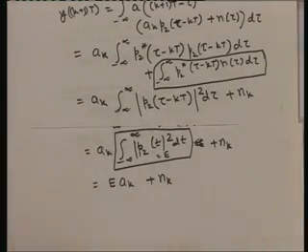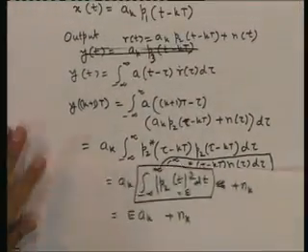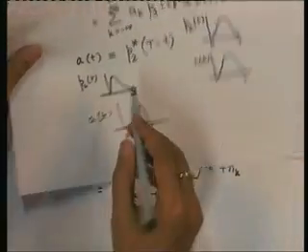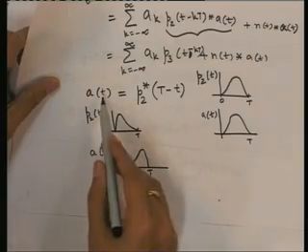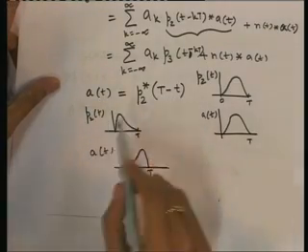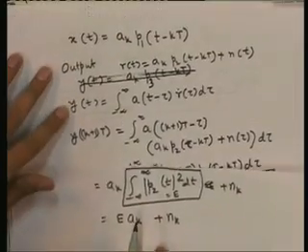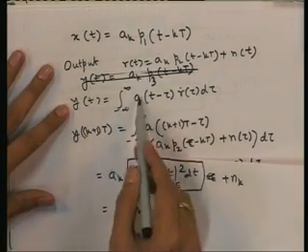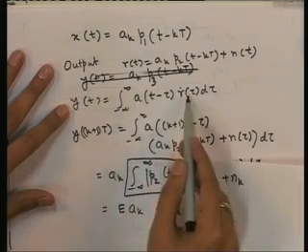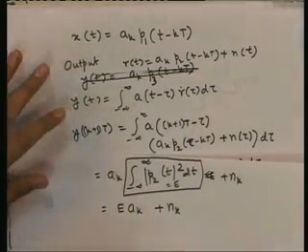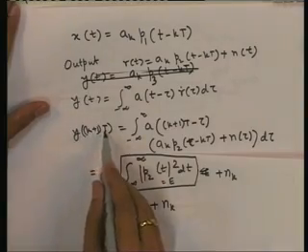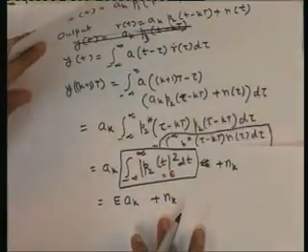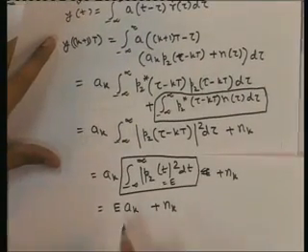So, what have we done here? We have taken particularly a matched filter. The receiver filter is the matched filter, and with that we have computed the output of the receiver filter, that is y(t), the convolution of the matched filter impulse response with the received signal, and that signal we have sampled at (k+1)T time. So, that sample value we have computed to be this.